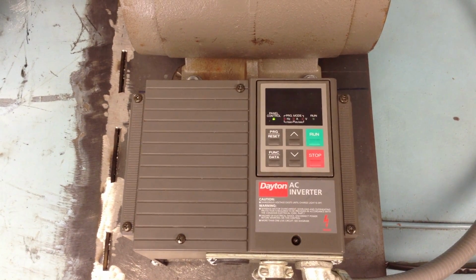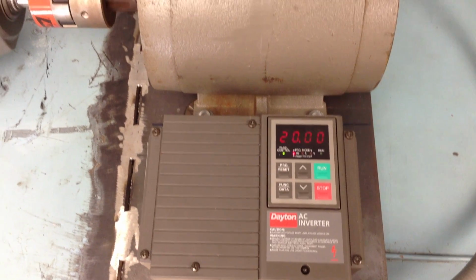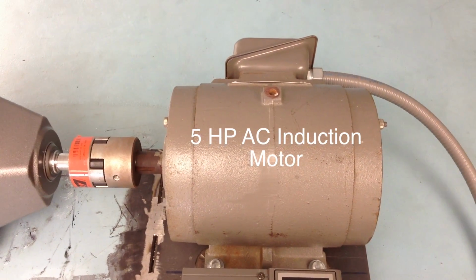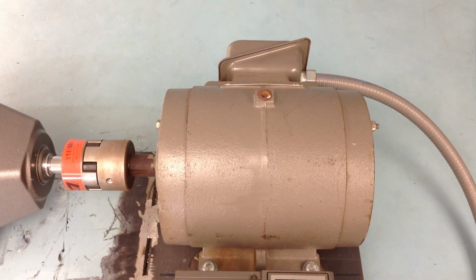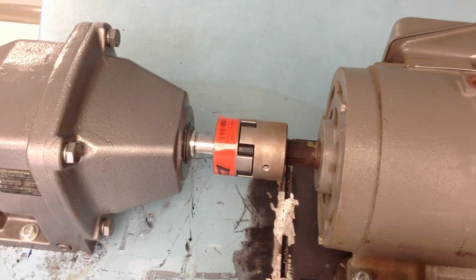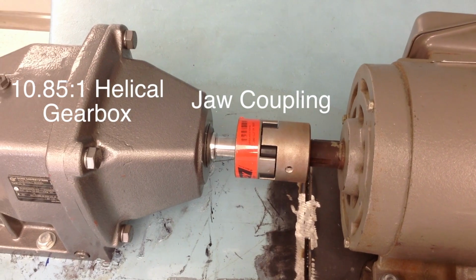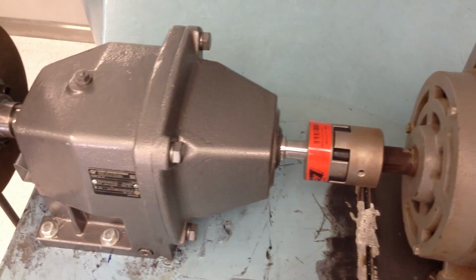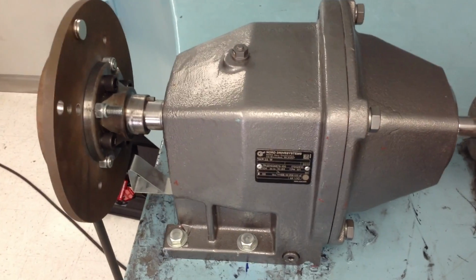The gust vane system is controlled through the use of a variable frequency drive connected to a 5 horsepower AC induction motor. The motor is connected to a 10.85:1 helical reduction gearbox through the use of a jaw coupling. The gearbox is then attached to a drive plate that is connected to the gearbox's output shaft.